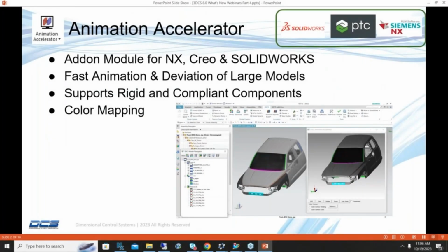Start with the Animation Accelerator window. So Animation Accelerator is a secondary graphics window that we have added for NX, Creo, and SolidWorks. The main advantage of this window is to have an improved animation and deviation speed when we are working with larger models. It also supports rigid and compliant components by applying the deformation on parts. And finally, we have also added the color mapping functionality into this window.